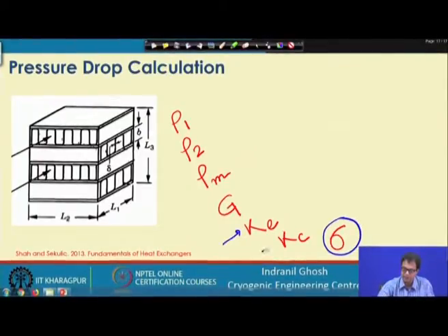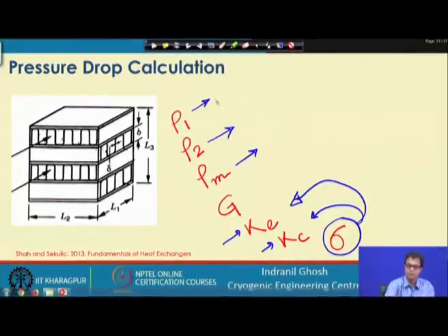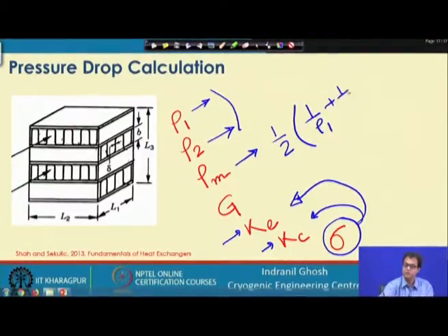Kc, Ke we have to estimate based on these sigma values. So, depending on the sigma values and the Re value, we have to estimate this Ke and Kc, and then we have to estimate rho 1 and rho 2, and based on this rho 1 and rho 2 we will estimate rho m as 1 by rho m is equal to 1 by rho 1 plus 1 by rho 2. So, from there we will calculate the rho m, and then we have to estimate G.